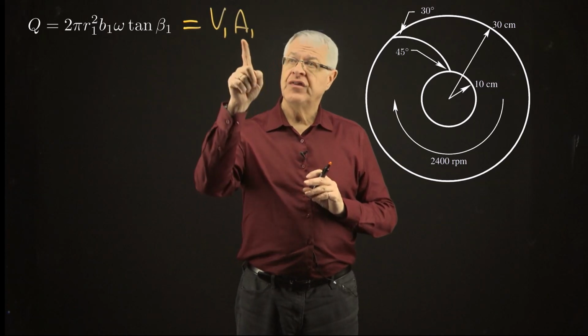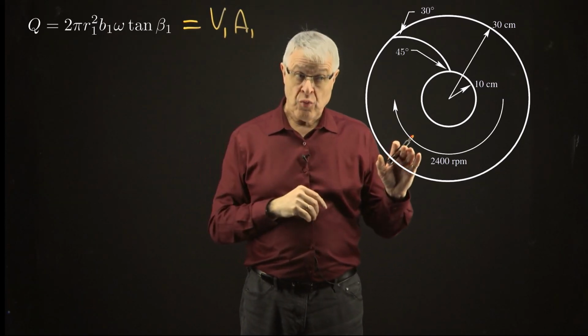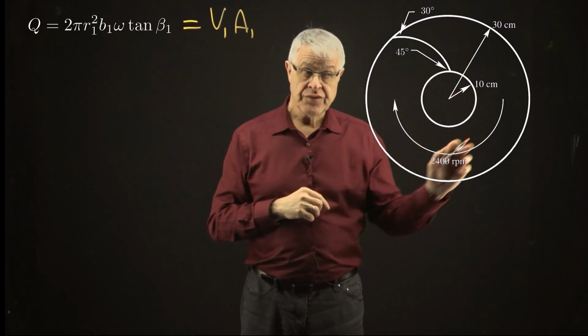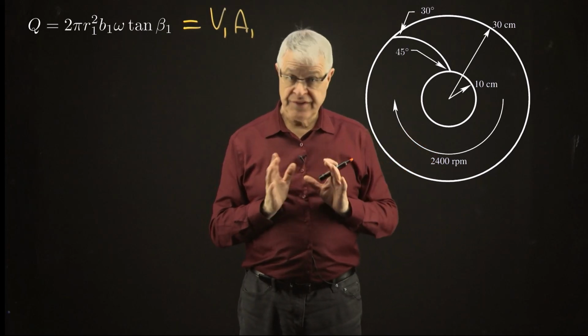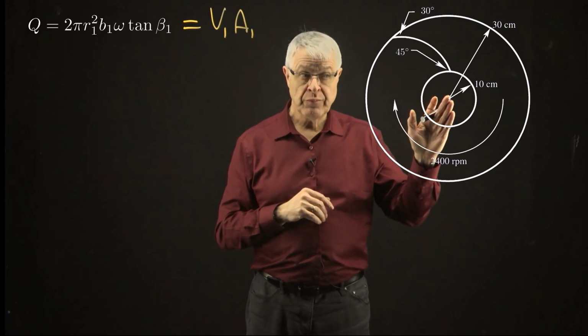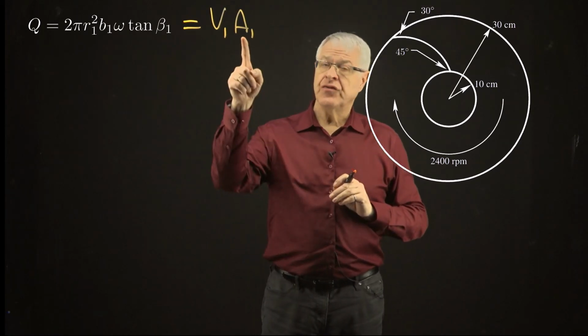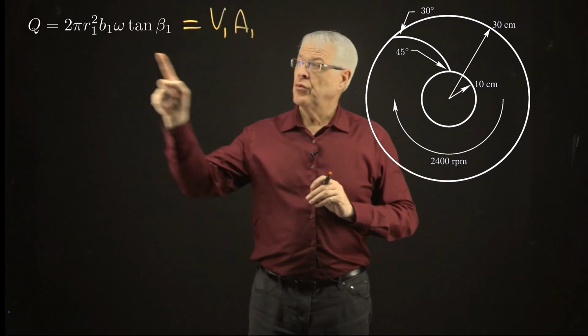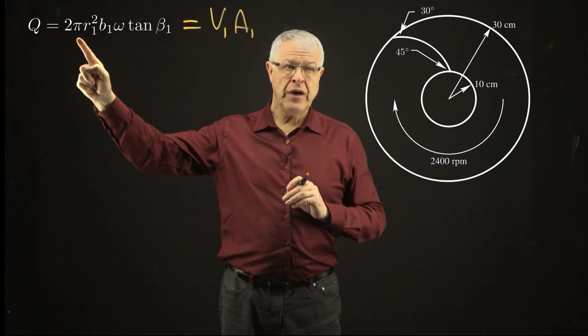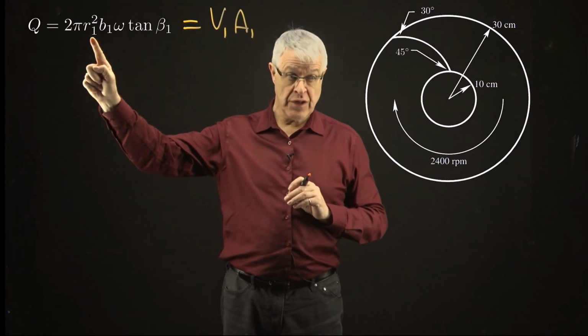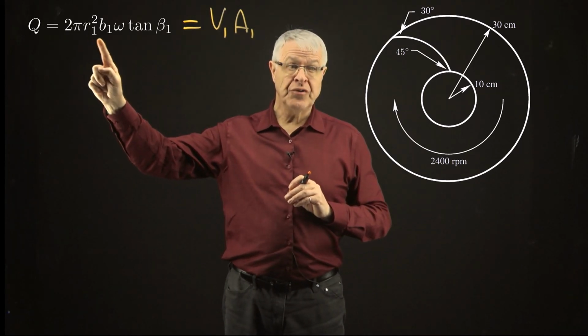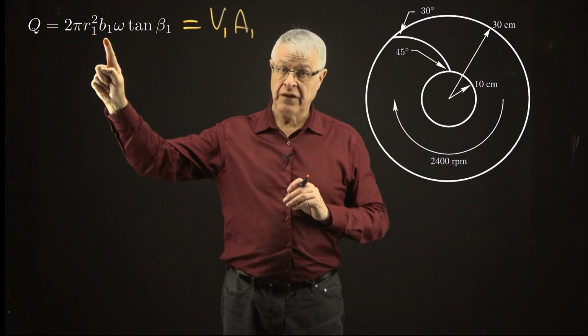So first of all, we see the area of 1. So remember, we're assuming uniform flow here. So the velocity entering the impeller is the same everywhere. Also, we're assuming pure radial inflow, and we'll get to that in a moment. So first of all, this area. Well, realize that 2 pi r is the circumference of that circle, multiplied by B1 will be the area.